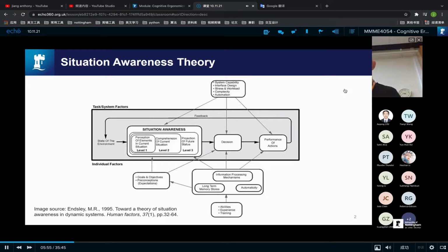There are other methods. So for example, if we're at the design stage, you could look at situation awareness requirements and do a method there. The process for that is that you would do interviews with subject matter experts, and then you would do some kind of goal-oriented task analysis. A very common approach is hierarchical task analysis, where you look at the overall goal. That might be monitor and maintain safe running of a nuclear power plant. Then you decompose that into monitoring the reactor core, monitoring the cooling loop, monitoring the overflow system, and then you decompose that further and further until you've got unit-sized tasks that you can then analyze and say, to do this subtask, what info does the operator need and when?